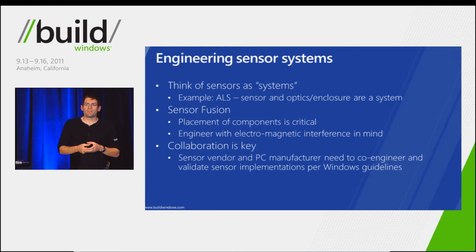A light sensor could have a dynamic range of 1 lux to 50,000 lux. And you might think that that translates to what the PC would measure in real life, but in reality, there's glass on the top surface. There's coatings on that glass. The industrial designers like to kind of hide the sensors away. Below that, you've got potentially other optics or a light pipe, that kind of thing. And what this does is there's an attenuation factor that you need to think about.